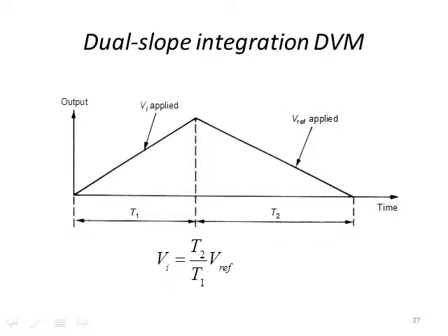So if you see your digital voltmeter, it will have a range that it can detect. And so you know now how this dual slope integration works, and you can see also that the reference voltage is used for calibrating the reference of the system. Also, the reference defines your input range for a digital voltmeter, for example. So if you have a voltmeter, it doesn't have an infinite range that you can detect. It has a finite range that's determined by Vref. Also, most of the common digital voltmeters will not allow you to go beyond 10 volts, between 0 and 10 volts typically.